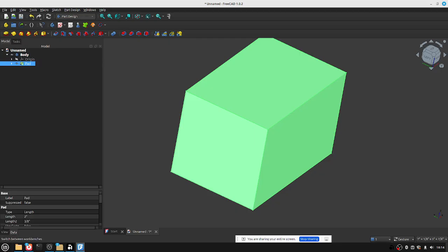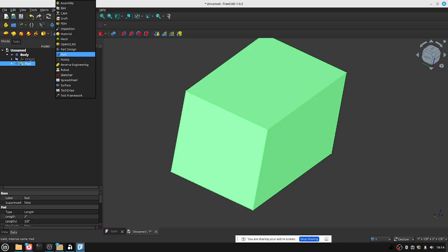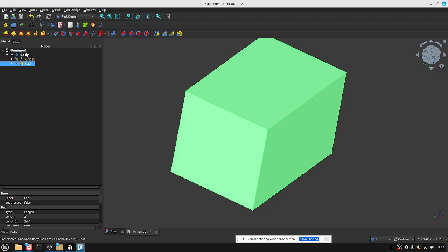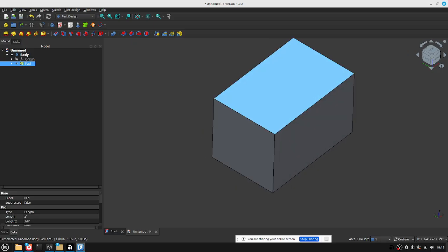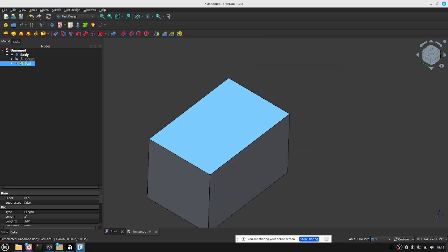Here's the cool thing about FreeCAD. So go back to, you can be in part design, but part design also has that sketcher thing in there. Click on that. Okay, so I want to draw features on this cube. So the new sketch, it's in part design and it's in Sketcher. It's the same function, right? It's just shared across different workbenches. Yeah, in this workbench it has that same function so part design has it, Sketcher has it, and it may be found in some other workbenches.